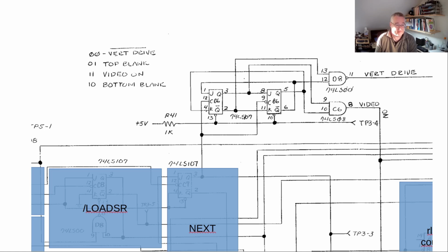And what is interesting is the two JK flip-flops that follow each other. You can see them, they have the same clock. If J is high, Q goes up. And then the second one, J is high, then Q goes up. But then if this Q goes up, and the next time K is up, so this one goes down. So it's not a counter, but instead it shifts the phases like so. It goes from 0, 0, to 0, 1, to 1, 1, to 1, 0.